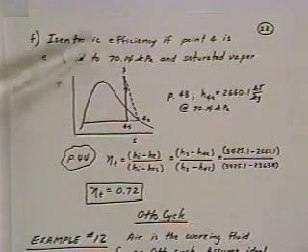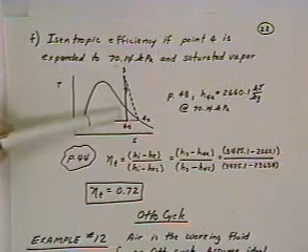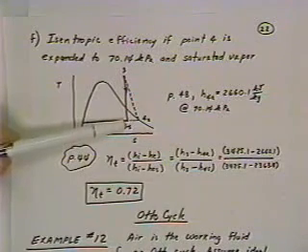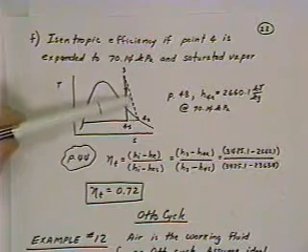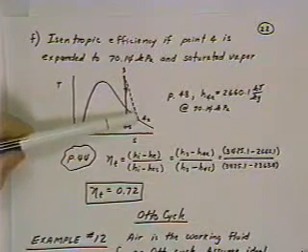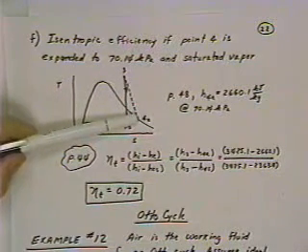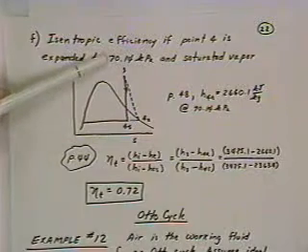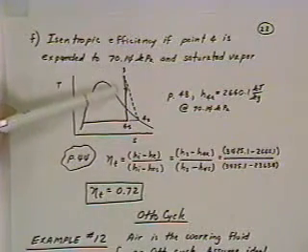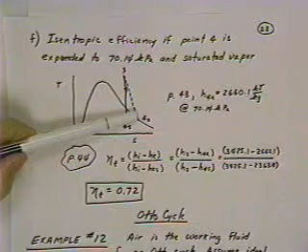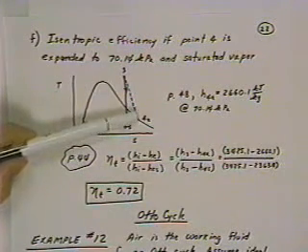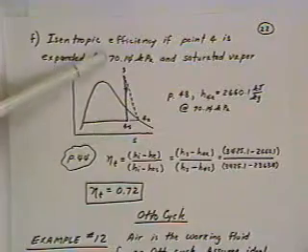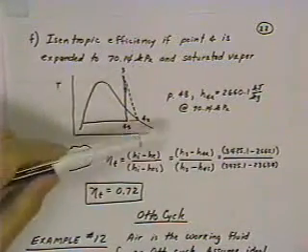And in this particular case, we're saying instead of expanding isentropically and reversibly down to 4s, the expansion really takes place irreversibly down to saturated vapor condition corresponding to 70.14 kilopascals. So the actual exit out of the turbine can be found at the saturated vapor condition at 70.14 kilopascals.